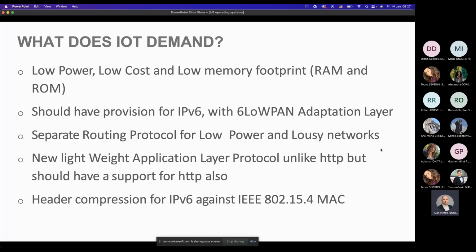Again, low power is key here. You'd like to have a radio transceiver that does its job and does its job without actually taking up a lot of energy in the process. So very low power usually means very low data rates or very small transmission ranges in the terms of meters or tens of meters for most IoT applications.